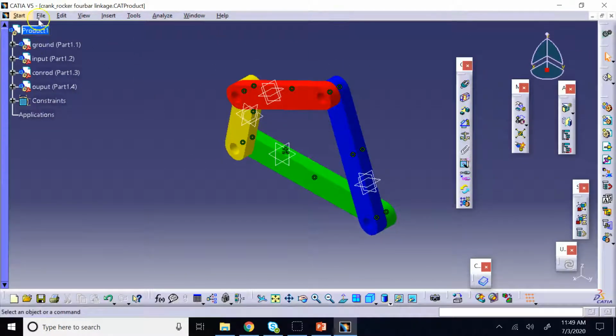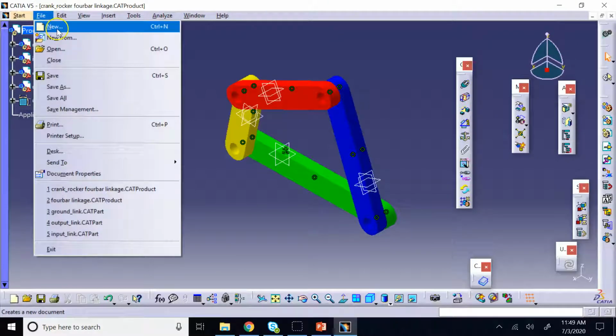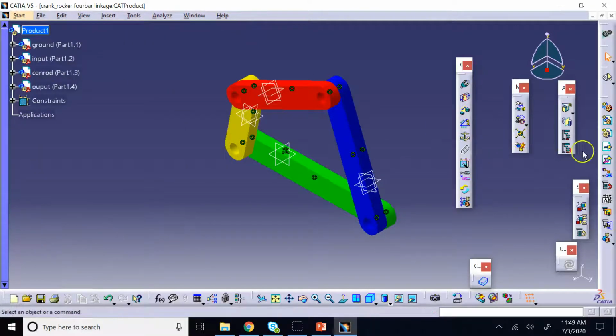So what do I do? Again, do you create a new file, a part, create that small cylinder, the pin, save it, then come back here and then go to existing component and bring it? Sure, you can do that. Or can you start creating the part without going to a new file or anything right from here? Can you insert a new component and start creating it while you are not even leaving the assembly? Yes, you can do that, and actually this is way more efficient, and I'll show you why.